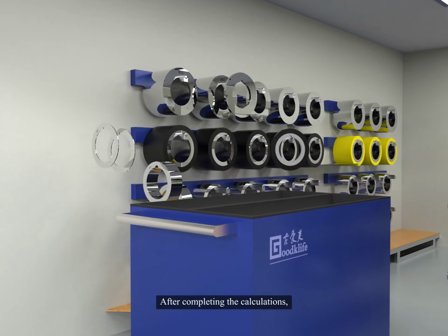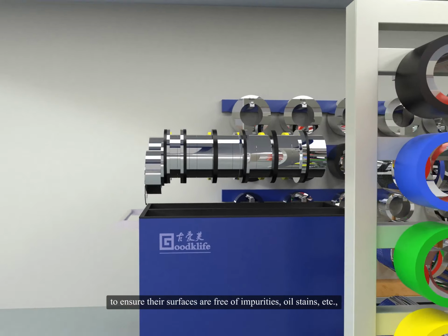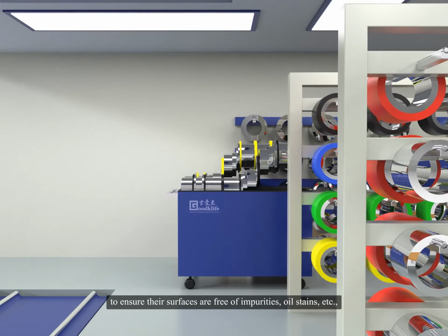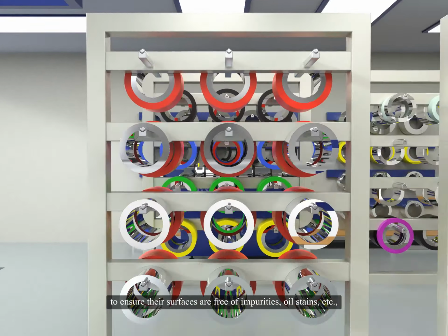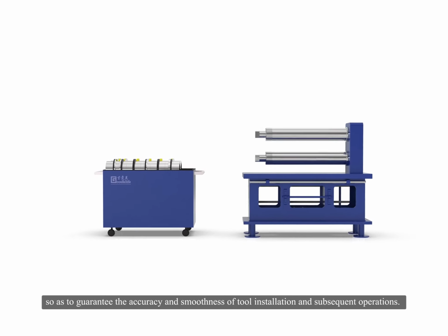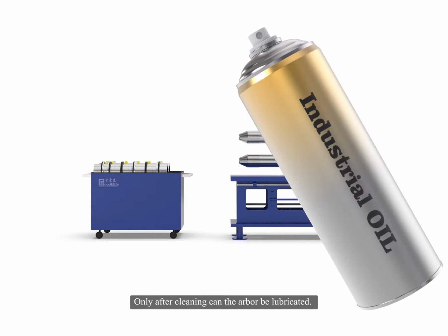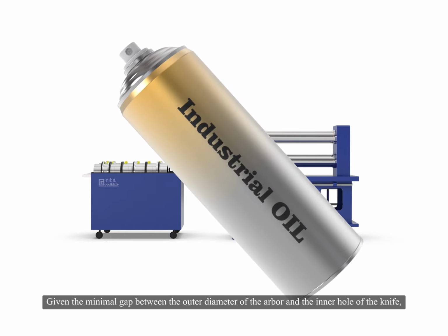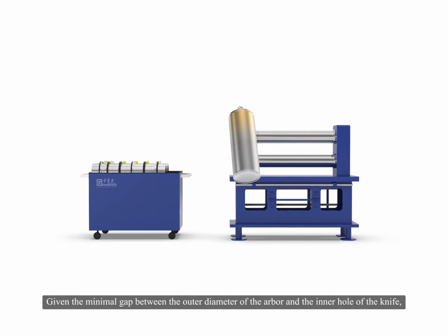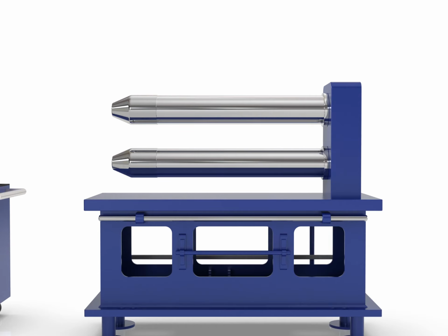After completing the calculations, all involved tools and related equipment must be thoroughly cleaned to ensure their surfaces are free of impurities, oil stains, etc., so as to guarantee the accuracy and smoothness of tool installation and subsequent operations. Only after cleaning can the arbor be lubricated. Given the minimal gap between the outer diameter of the arbor and the inner hole of the knife, applying lubricating oil can effectively facilitate the smooth installation of slitting tools onto the arbor.